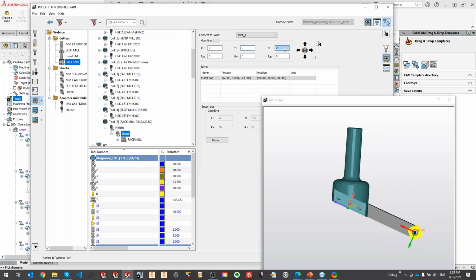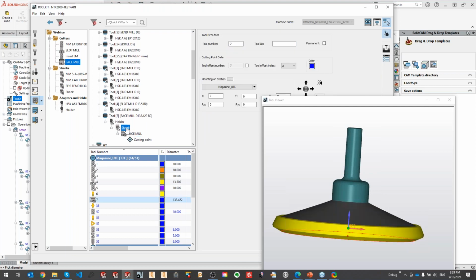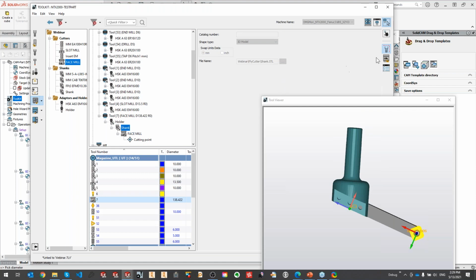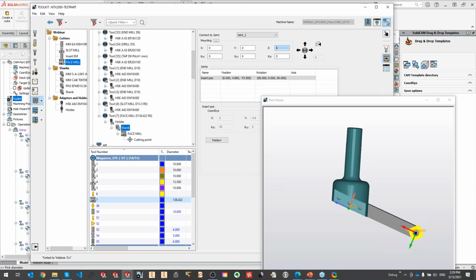So I can do it parallel to this one actually, with the shank position like this, to move it along the z-axis of the shank itself. But what if I want to do that at the cutting point here? So let me show you how to define this. Imagine that you don't have this, you define maybe a different vector or something, you can actually create your own linear axis that you can later control. So let me go to the tool components level.